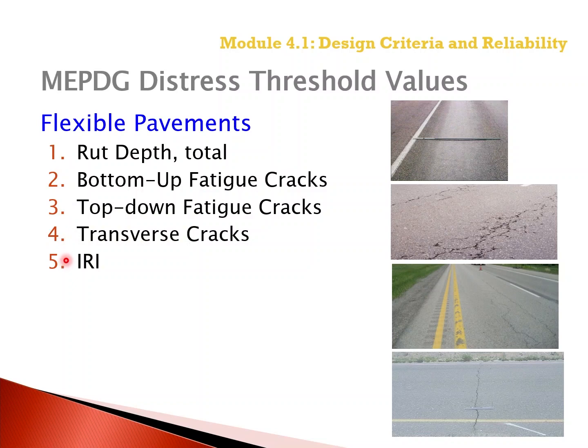The user might remember that the initial IRI is on the same screen. The initial IRI is not used to judge the acceptability of a design, or it's not considered a distress threshold value. But it is important to know what the starting value of IRI is for each pavement design strategy. So the initial IRI is included in the MEPDG design threshold values in the software itself.